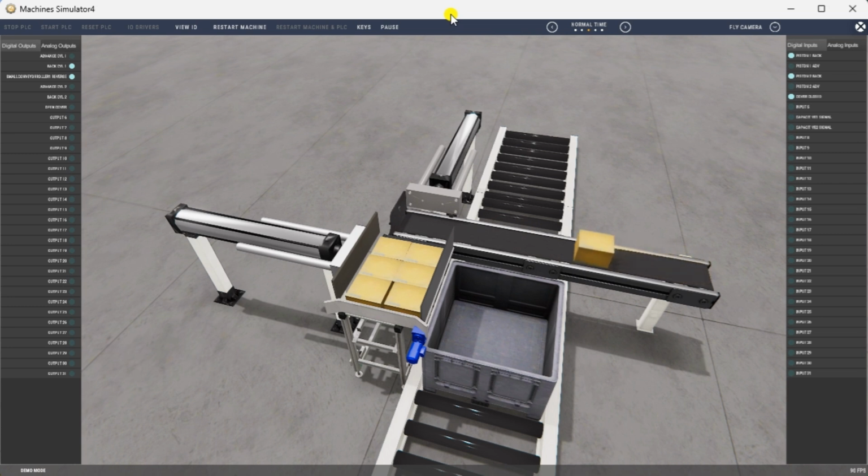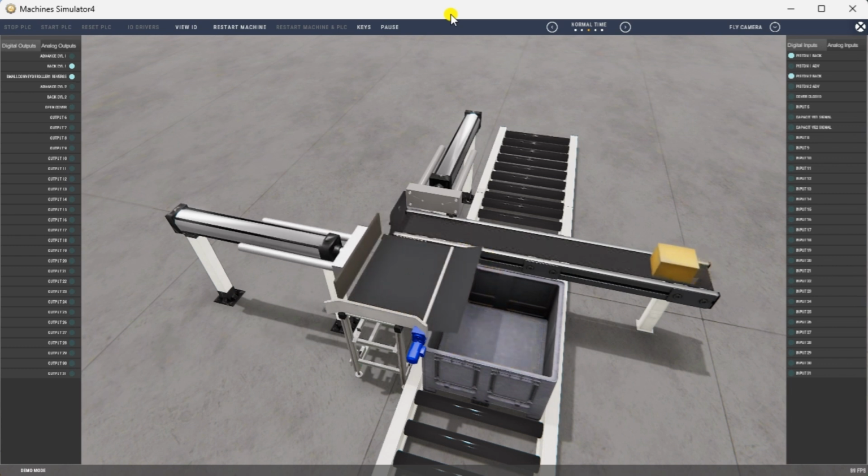When the loading dock has 8 boxes, the cover will open. After the cover is open, cylinder 2 pneumatic pusher will advance until the piston 2 advanced sensor comes on. This ensures all the boxes are pushed into the crate. When cylinder 2 retracts all the way, the cover will close. The cycle can then start over again.